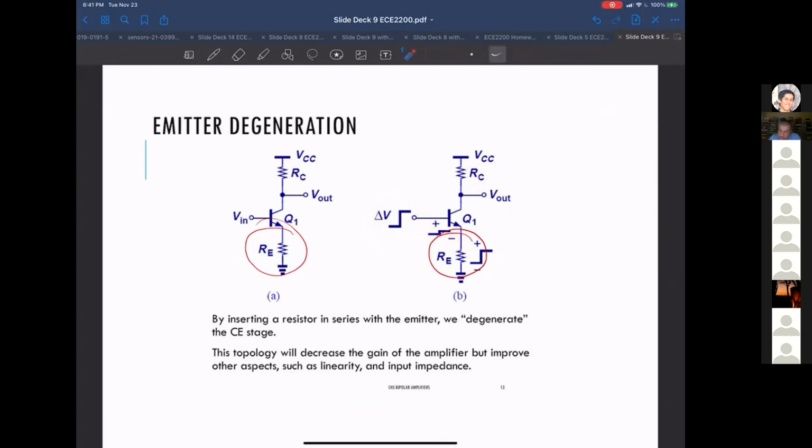An exponential basically means a lot. So you can get a lot of gain. That small bit of voltage change here gives you a big change in current, and that big change in current times a resistor gives you a big change in voltage out here. So high gain, get that? Okay, so that's really good.